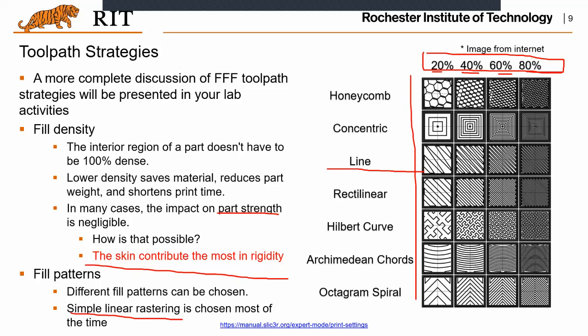But there is some recent research looking at, besides these built-in patterns, whether we can optimize the infill by checking the load this part will take and doing topology optimization for each layer, such that there is customized infill for each layer, expected to be the optimal one.